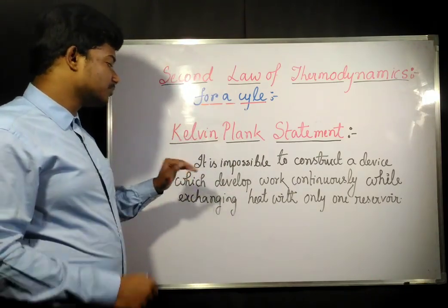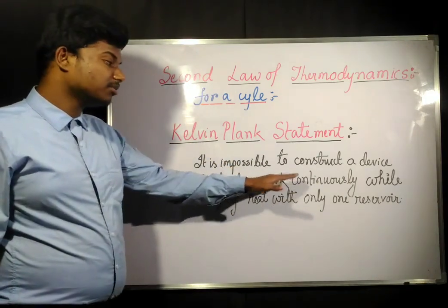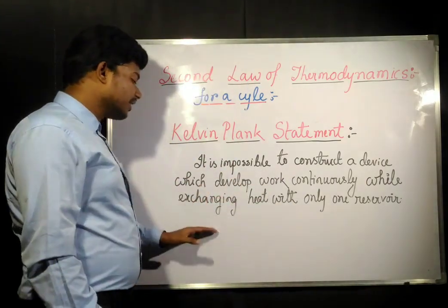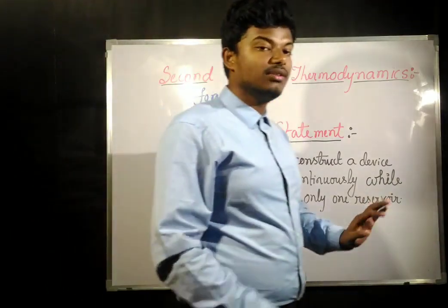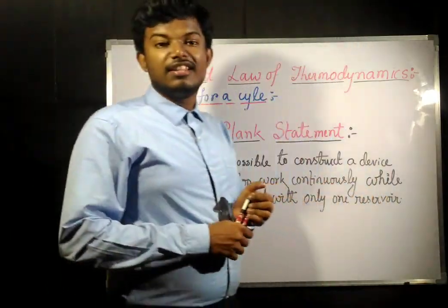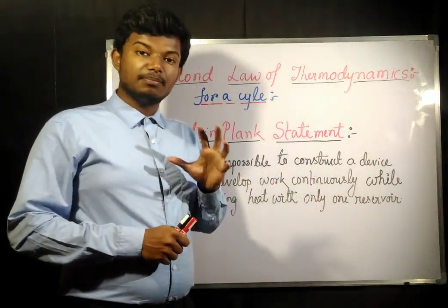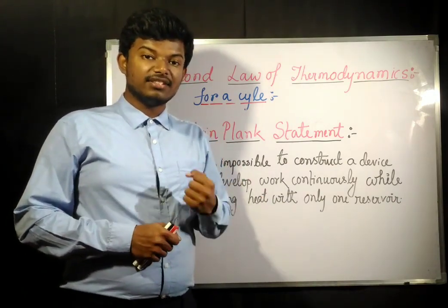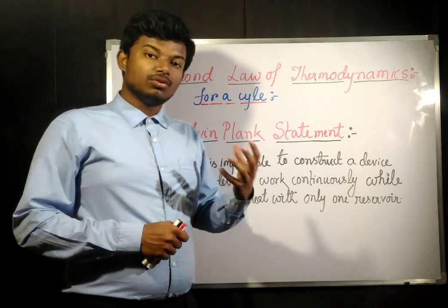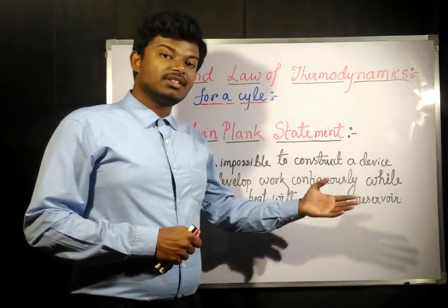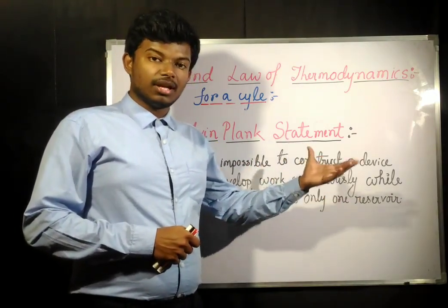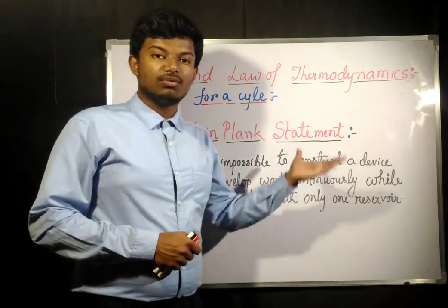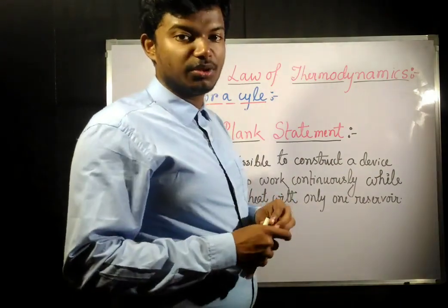So according to this statement, what happens? It says that it is impossible to construct a device which develops work continuously by exchanging heat with only one reservoir. Okay, that means it is completely impossible to construct a device which can give continuous work by exchanging heat with only one body, or only one thermal reservoir.